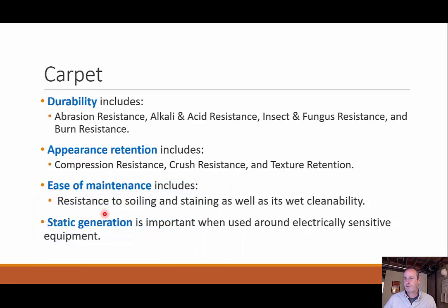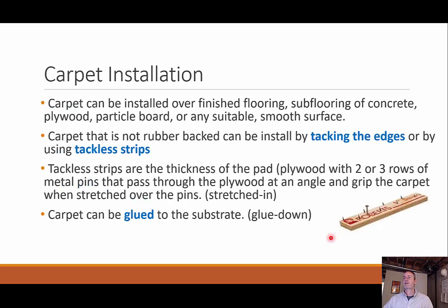Ease of maintenance, resistance to soiling and staining. How easy is it to clean? And then that static bit, right? What about if I'm working in electronically sensitive equipment? What if I'm in a computer lab? What kind of carpet? How would that be different than if I was just in a normal household application? Or if I want to shock my sister? What about installing the carpet? It can be put directly over finished flooring, subflooring, concrete, plywood, particle board, almost just about anything, right?